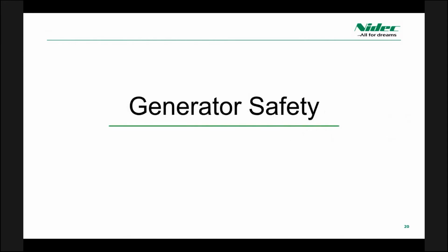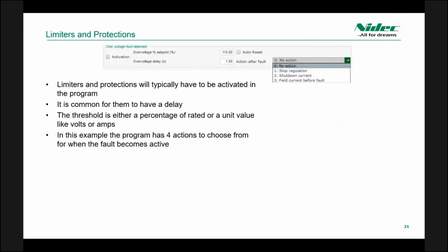In this section, the protections and limiters are going to be taken from the EasyReg Advanced software, which is a software used to configure our D350, D550, and D700 regulators. This graphic shows what the protection set points look like. The protections will have to be activated by a checkbox.